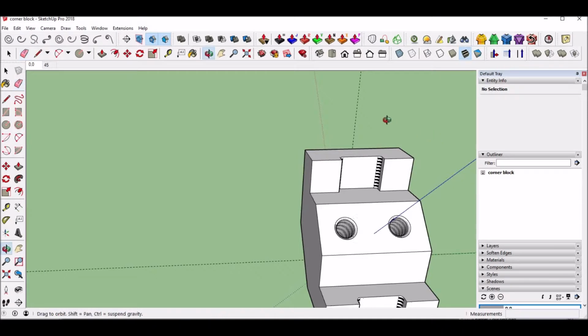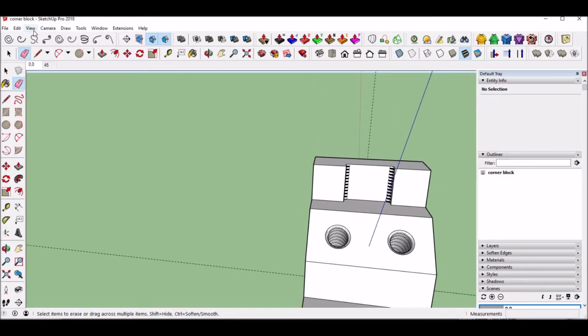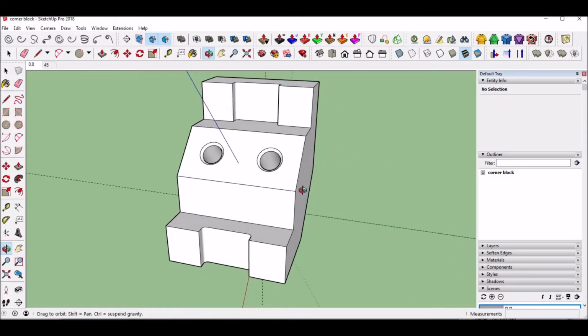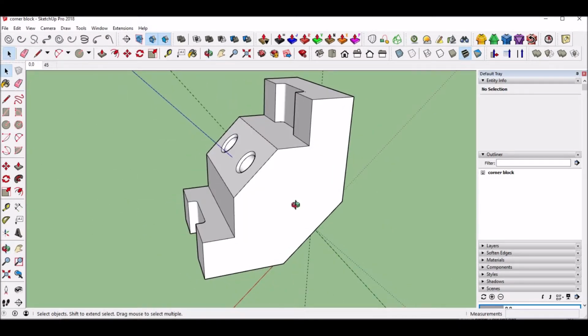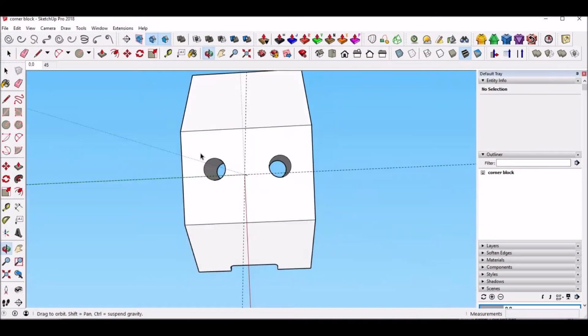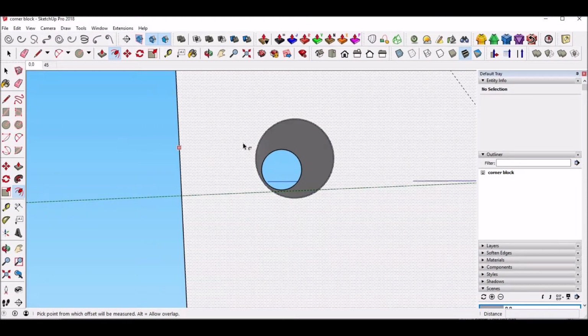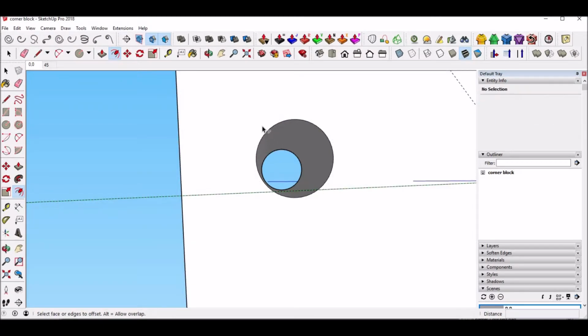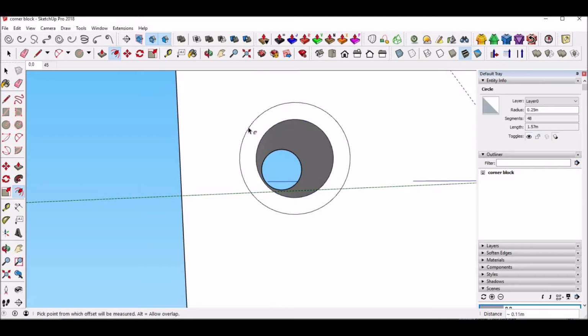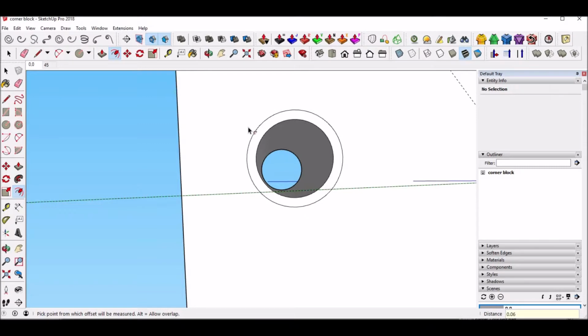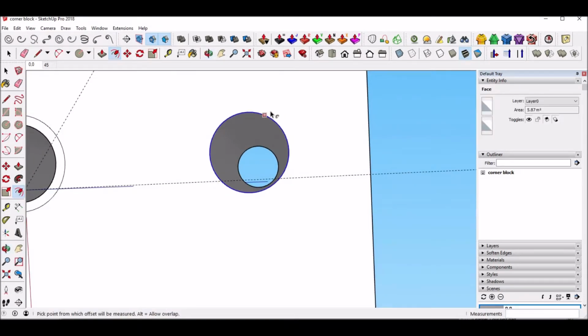Okay, we're good. Alright. So go to View, Undo, Hidden Geometry. Okay. Now we have chamfers there. So let's do the same thing here. F for offset, and we're going to click on this, and we're going to, I hate when it does that. No. Okay, look. Click on the circle. There we go. Thank you. 0.06. And then this one's going to be the same, 0.06.